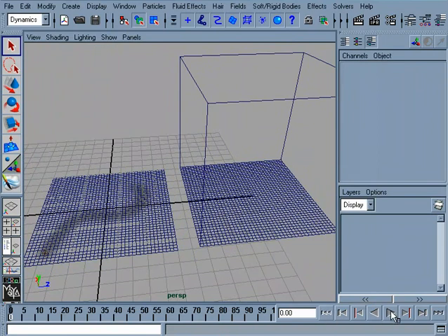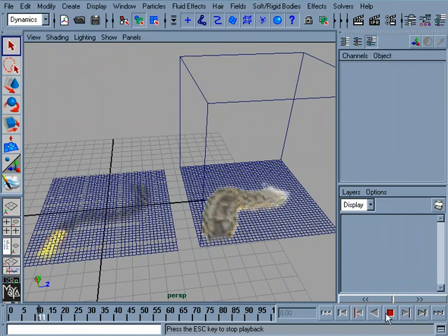Now let's see if this is going to work. So we play this back, and we let this do its thing, and now we can see, okay, now that there's a certain amount of temperature in this area, it's going to ignite the corresponding voxel over here. Now we do actually have a pretty serious problem, and you can see that this fire is happening a lot faster than what this gasoline trail is burning along. So let's see what we can do to fix that.